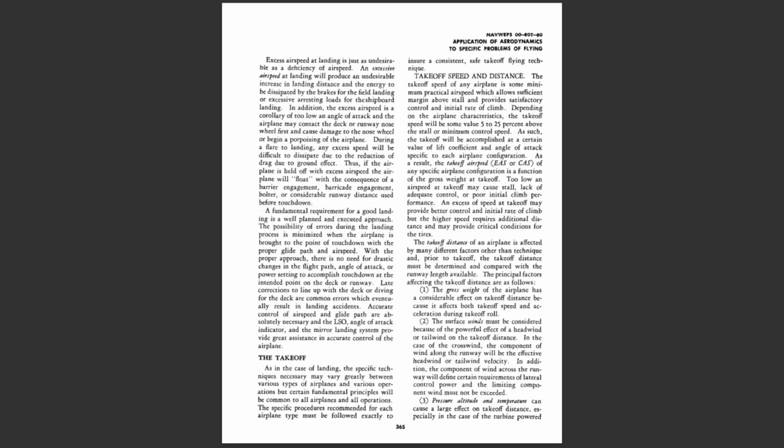Excess airspeed at landing is just as undesirable as a deficiency of airspeed. An excessive airspeed at landing will produce an undesirable increase in landing distance, and the energy to be dissipated by the brakes for the field landing or excessive arresting loads for the shipboard landing.